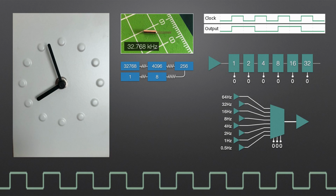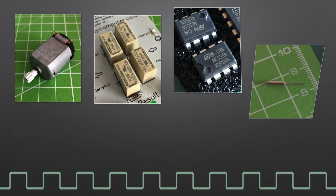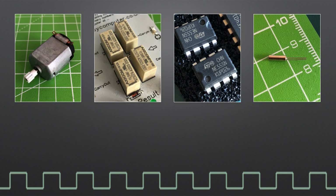And being honest again, this design is neither unique nor new to the computer. This is exactly how the little temporary timing board works I've had in my computer for some time. I adjust the clock frequency via the dip switches, which then picks off the appropriate frequency from the ripple counters. So, 4 different options, but what to go for?